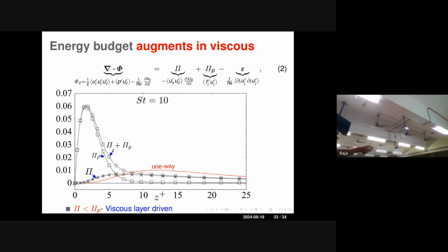Then we went ahead and tried to include even the pressure terms in the system, to see how the pressure fluctuations change on these structures, and particles have a big influence on those structures. Basically, the overall result is that when you have particles in the system, the logarithmic layers are disrupted, but the viscous sublayers get modulated and we start creating more and more turbulence in the system.